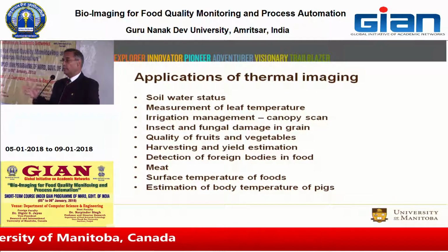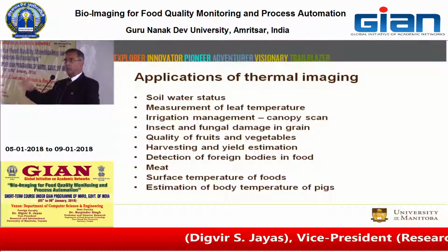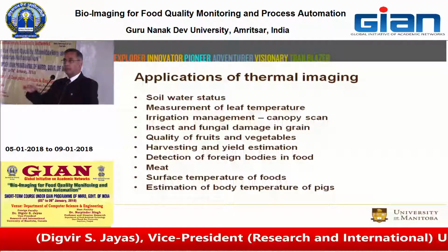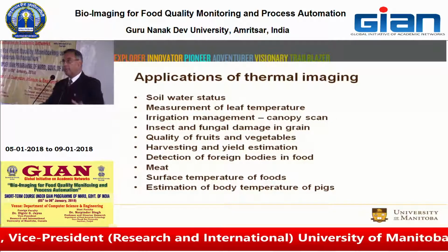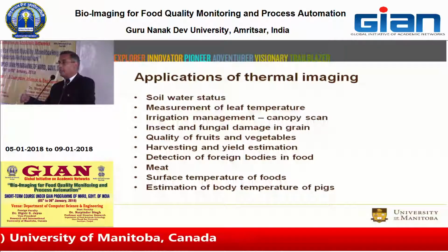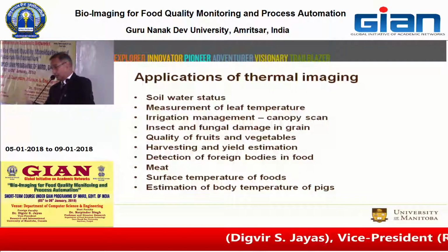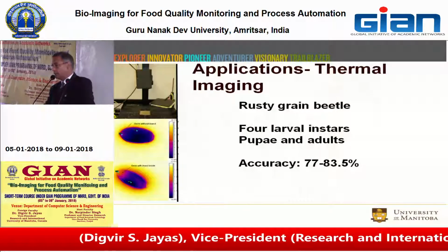So you would not be able to detect that. But on the other hand, if that spoilage was occurring closer to the wall, then the wall would see a temperature difference and you'll be able to detect that. So the one thing you have to keep in mind is that it measures the temperature differences on the surface of the object, but not inside the object. Okay, and anytime you can detect that, thermal imaging can be used.